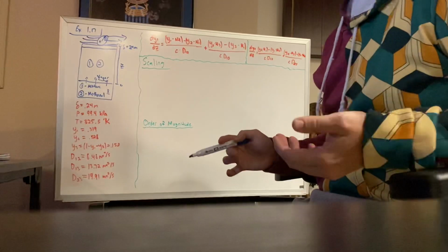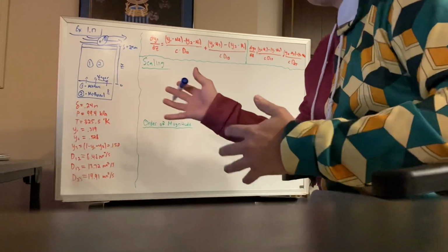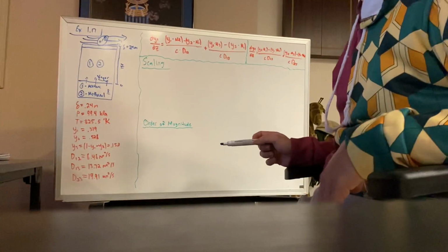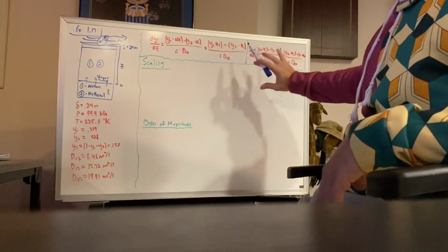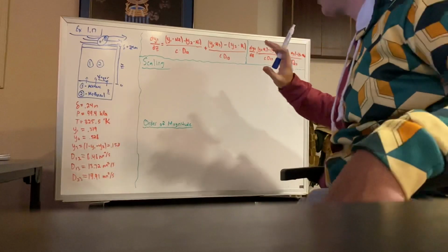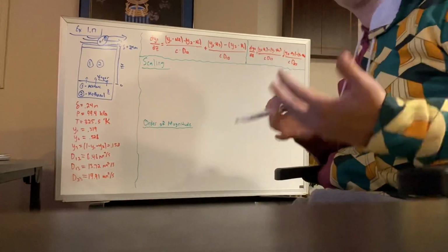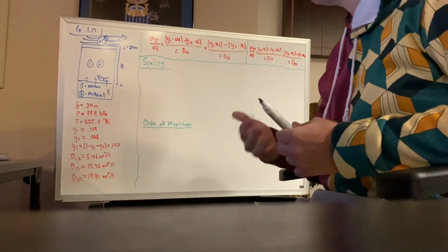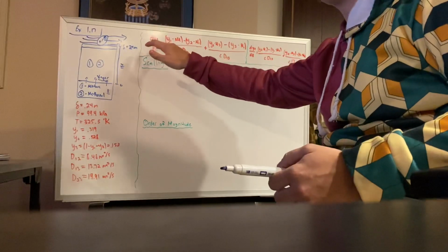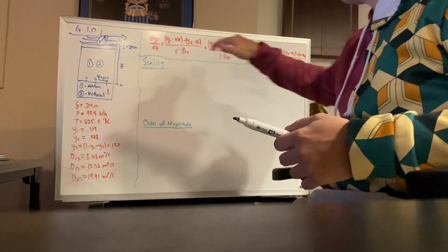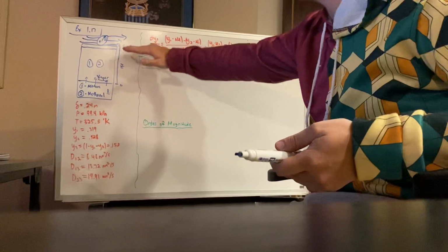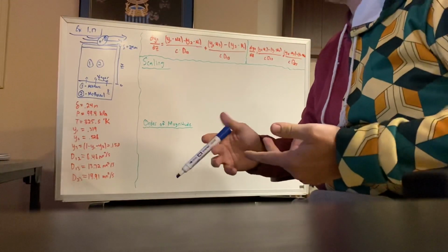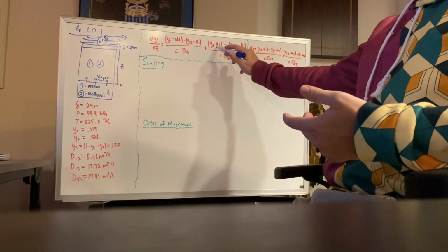And so to start, we'll examine and analyze what we're really dealing with at the current moment. Up here, I went ahead and wrote down the Maxwell-Stefan diffusivity equations for component 1 and component 2. And this is really the rate of change of the mole fractions of component 1 and component 2 with respect to Z, which is the vapor phase as it moves through it.